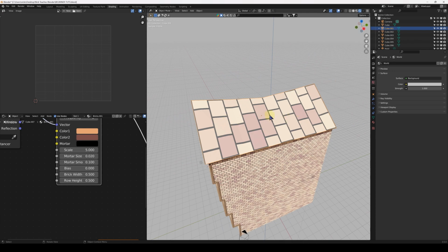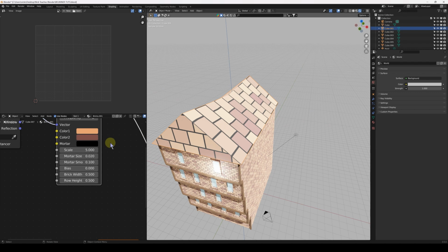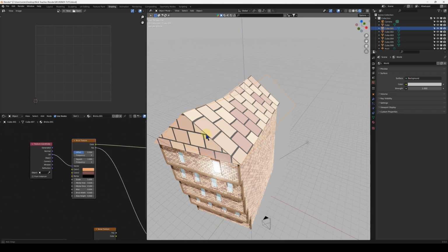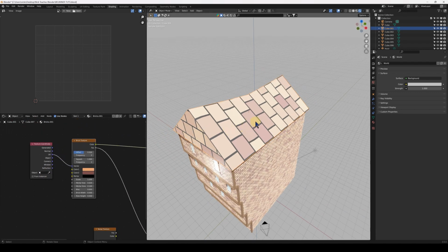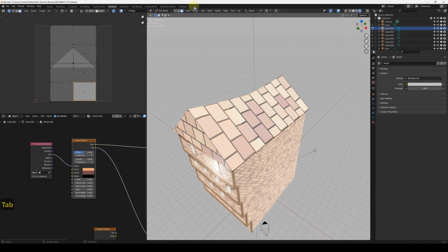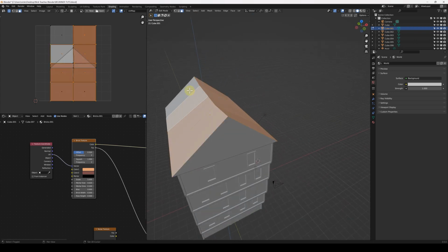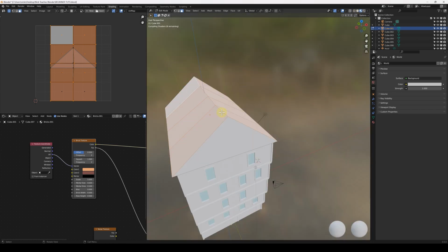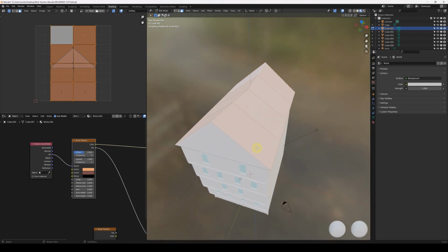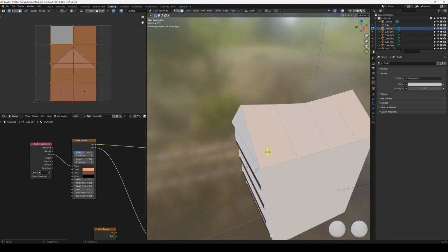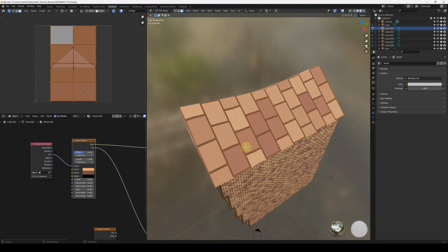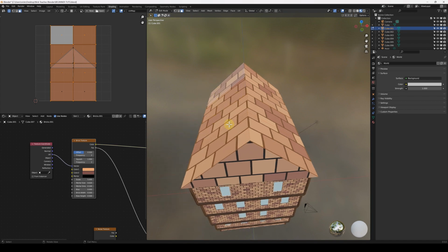What we want to do now is rotate these because they're facing the wrong way. We can do it a number of ways, but a pretty quick way is just using the UVs. So if you tab into edit mode, make sure we've got face select, and just select these. This is where material preview mode is pretty useful, when they load up. It's just got to load up the shaders and eventually we'll see them. If we select all these faces, then we'll see them all here.